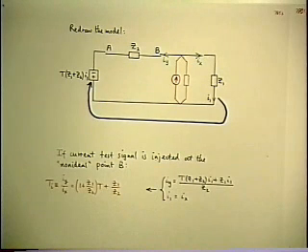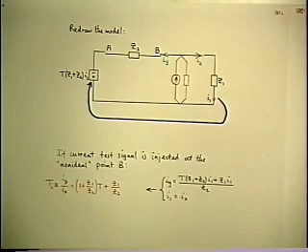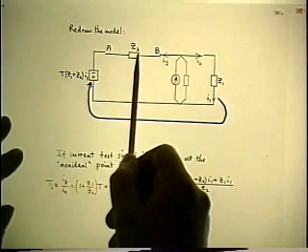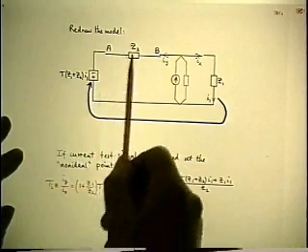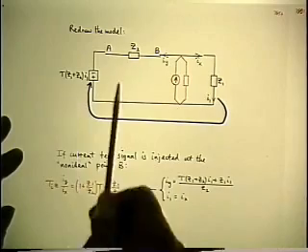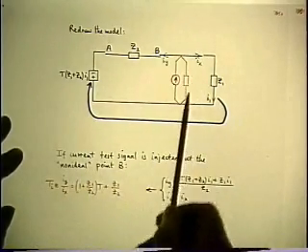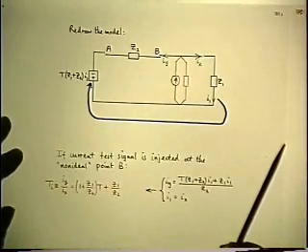Not surprising. And the only difference is it's the ratio upside down that matters this time. Z1 over Z2 has to be small, which is the same thing as saying that the Z2 has to be a very high impedance, meaning that this works when you have a current source and not a voltage source on the left-hand side, which we already know is the ideal case when you would use current injection anyway.